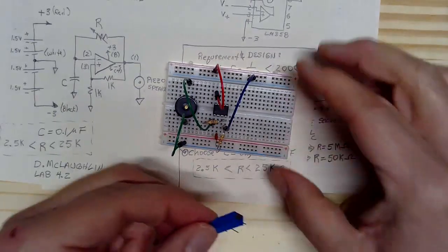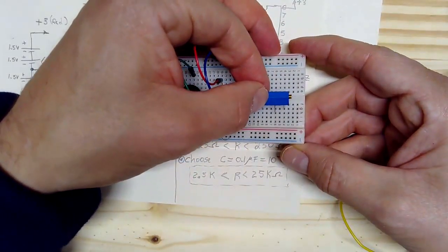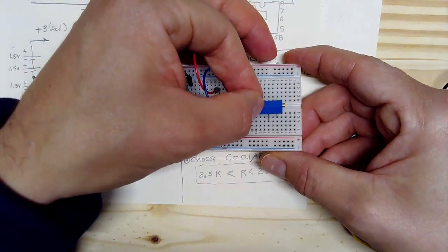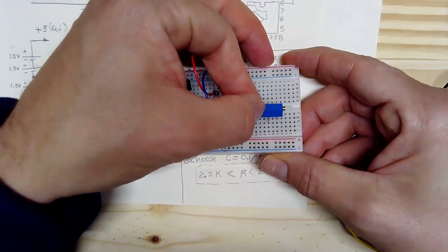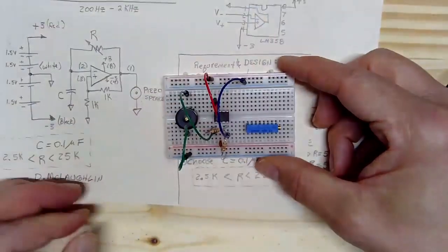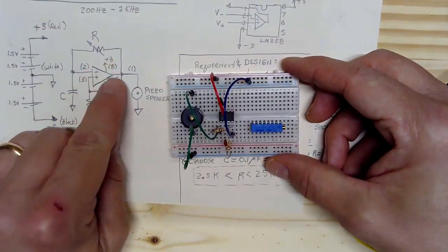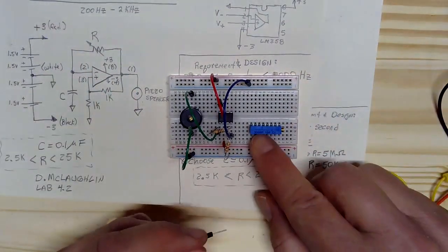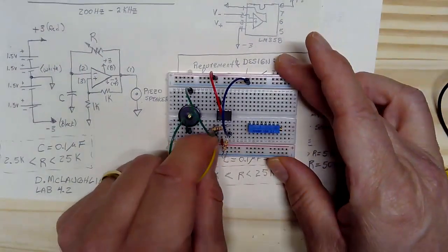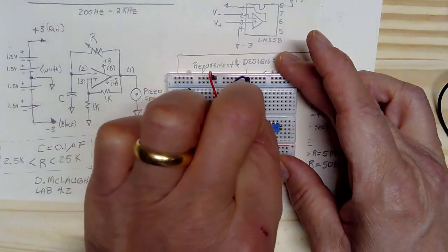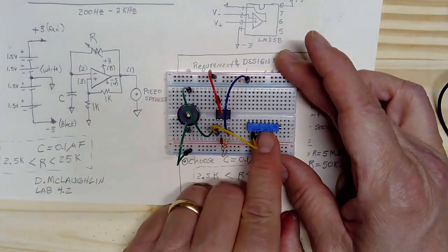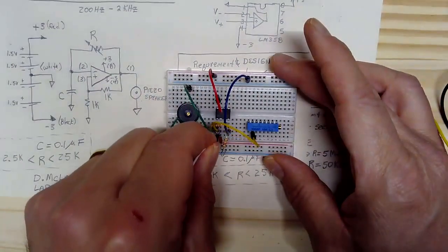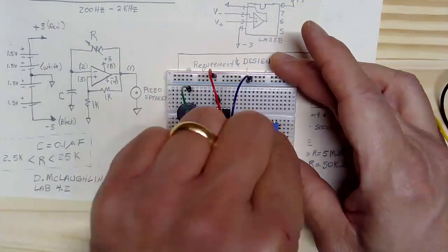Okay, so I'm going to pop this into the circuit board, and I also have to keep an eye on where I'm plugging it in, because once you put it in, you can no longer see the little leads. The wires that we need are going to be on columns 7 and 10. This resistor goes between pin 1 and pin 2 of our op amp, and then it's going to columns 7 and 10 here. So pin 1 is going to go to 10, and it doesn't matter which goes where. It's just a resistor. You can turn it around, it's not polarized. We said pin 1 and pin 2 are going to go between 7 and 10.